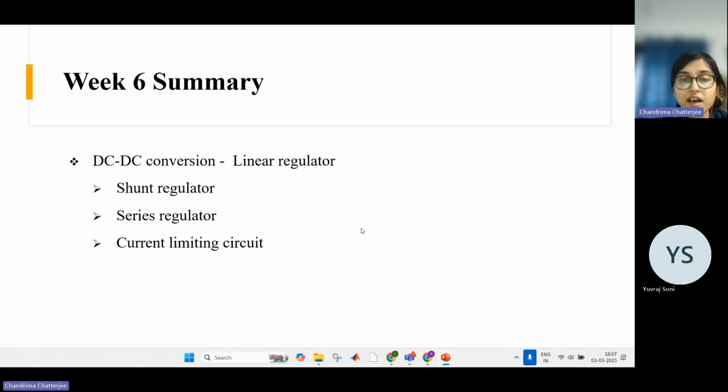Last week we discussed different current limiting circuits for diode bridge rectifier, which comprised of resistive solution, thermistor, then transformer, like limiting the inrush current with transformer. And we also saw the op-amp circuit and the contactor and relay circuit, which we usually use for limiting the inrush current.